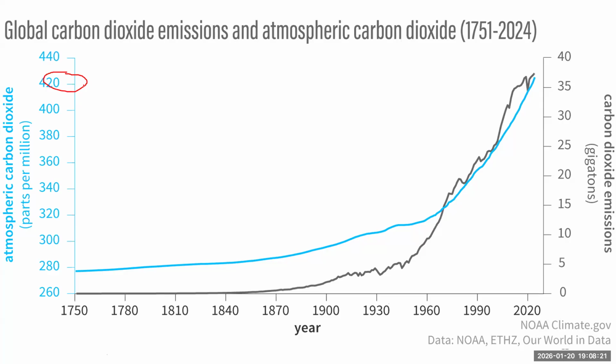If you are a building engineer, for the design of your air conditioning system you need to introduce outdoor fresh air into the indoor environment to remove the carbon dioxide and provide fresh air. Then the calculation is very important, as is the intake louvre location, to make sure the fresh air has relatively lower ppm carbon dioxide concentration levels.